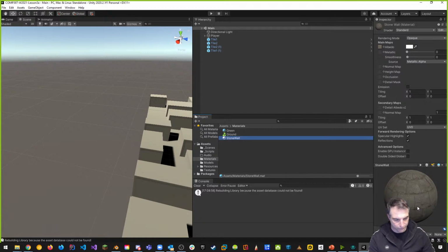So a normal map fools the camera into thinking that there is depth on a model when there's actually not. It uses the dark areas and the light areas in the model to create the illusion of depth, by changing the color of the pixels around from the sample that we're getting. So it's not a displacement. We're actually not changing the model at all when I use a normal map. All it's going to do is, towards the normals, which is the direction the face of the model is pointing, we're going to change the object so it looks like it has depth.